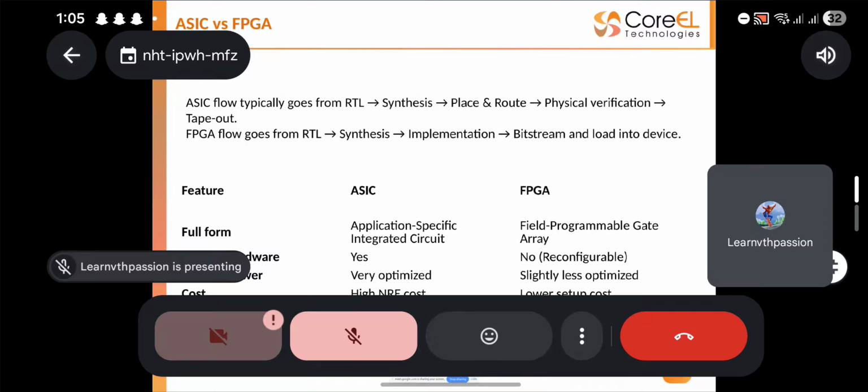If it passes the verification, it's not like it's ready for the foundry tape out. Because the set of rules which is given here is at a very lower level, it's not industry oriented. Industries will have a different set of rules and different DRC checks, where they will run multiple design rules. Here there will be a limited set, just for your understanding and to go with the flow. When it comes to the industries, again there will be a different scenario.